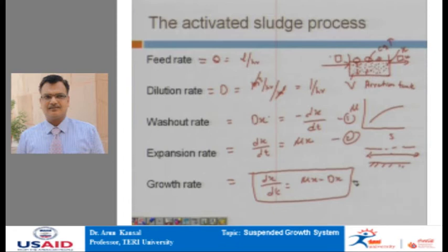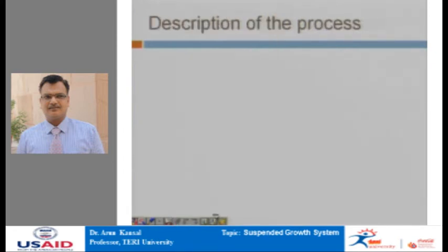In a continuous flow reactor, now I am showing you again, suppose this is the aeration tank under mixed condition. Wastewater is coming in, wastewater is going out, it has a particular volume, it has some initial biomass concentration in the tank, and it is getting fed at the rate of Q liters per hour. In this system, the initial BOD I am denoting with the symbol S0, that is the initial amount of the BOD or food coming into the aeration tank.